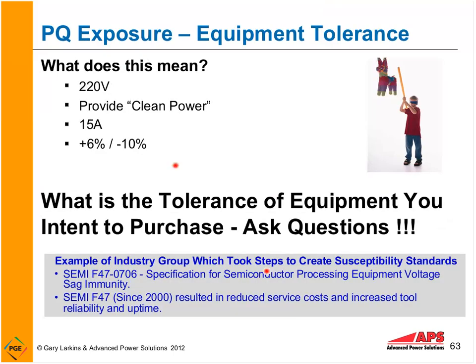Here's an example, by the way. I've talked about power tolerances. This one manufacturer, they published, this is their power tolerance. 220 volts is what they said they wanted on the input. Well, that's a non-standard voltage in the US. Right away, that's a red flag for me. And they actually meant the 220 volts.